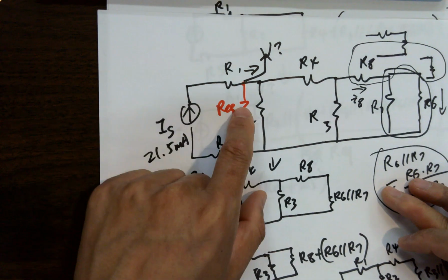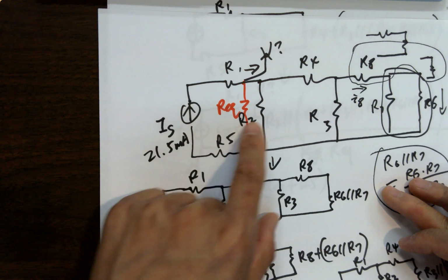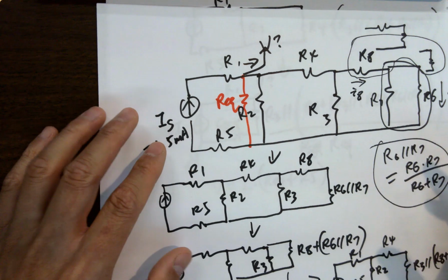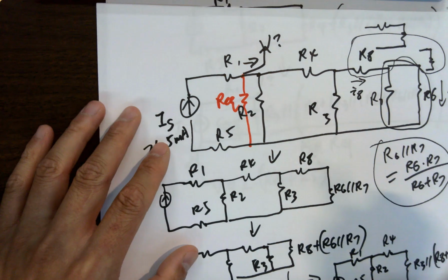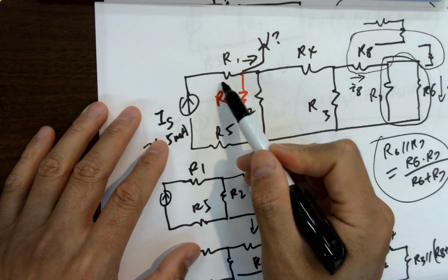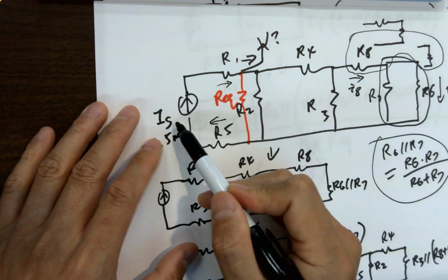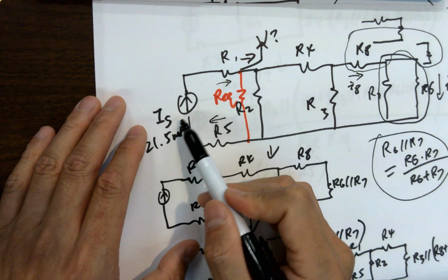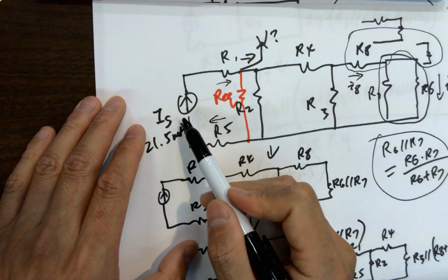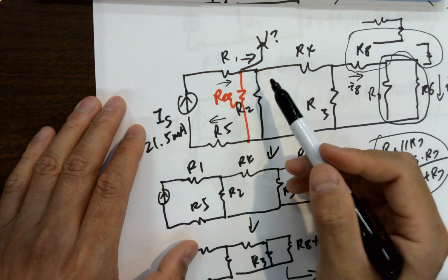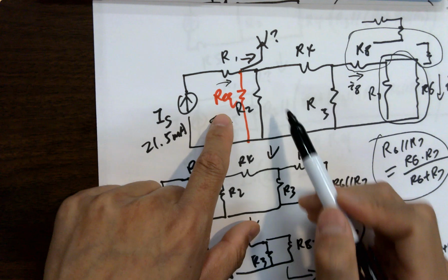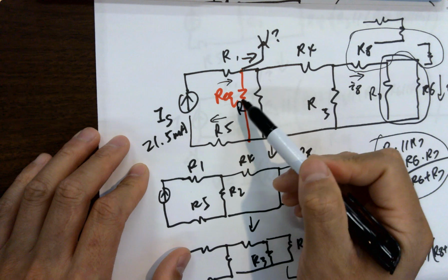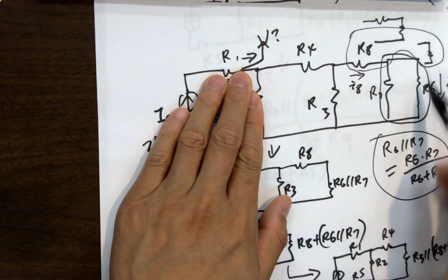It's the same resistance. The only thing that determines the voltage is the resistance, because you've got a current, and it's the same current. Another question here. The current flows through here and here. Is it going to change if I change the resistance here into the equivalent resistance? Is this current being changed? No, it's the current source, not being changed. And another question: is the current flowing through the equivalent resistor equal to the current flowing through the entire black box?